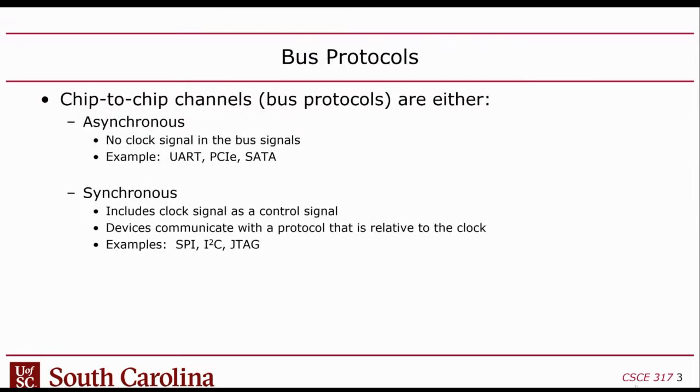This is another kind of conceptual thing. Chip-to-chip channels, also called bus protocols, is, like I said, kind of the older term. They can be asynchronous or synchronous. Asynchronous is when you don't have an explicit clock signal inside the channel.